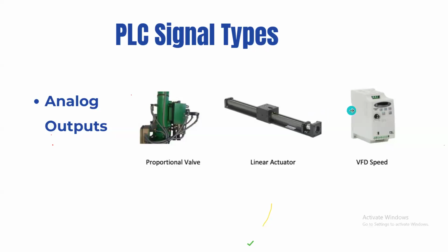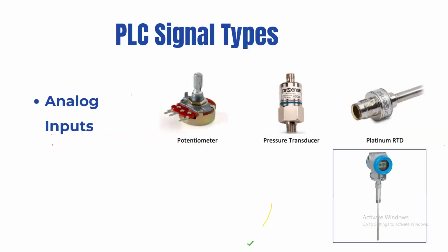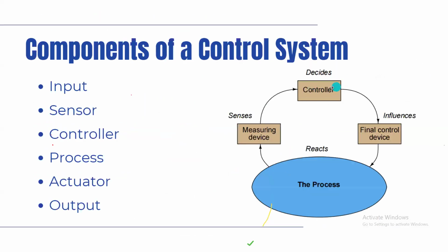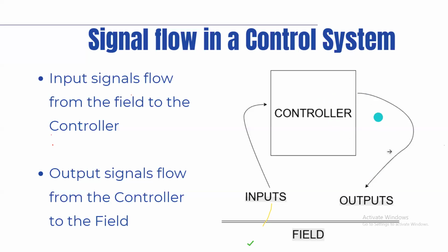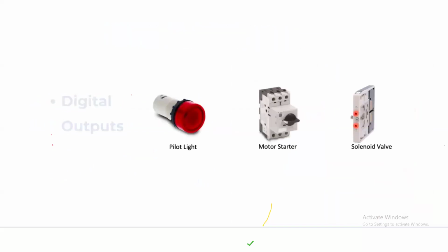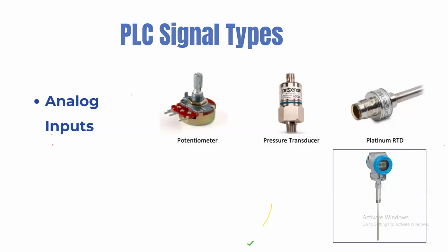But first, if we are just to give a very simple answer, I told you that for an analog input, your point of reference must always be your controller. Your controller is the one sending the speed command to the VFD. That would be an output because your controller is the one trying to vary the speed of the VFD. But there are devices that may not function as just one signal.